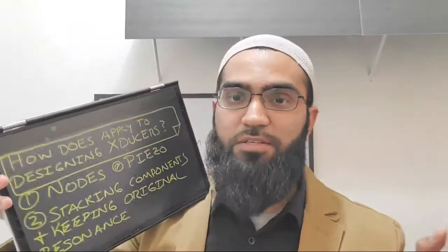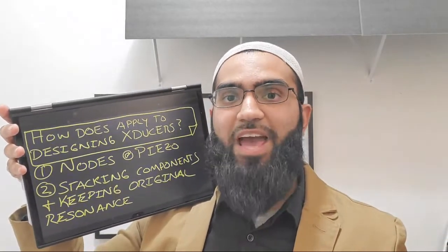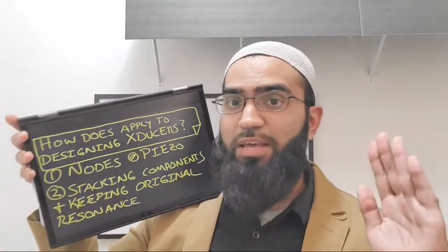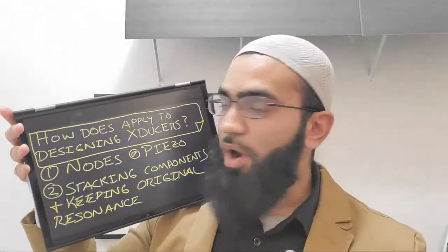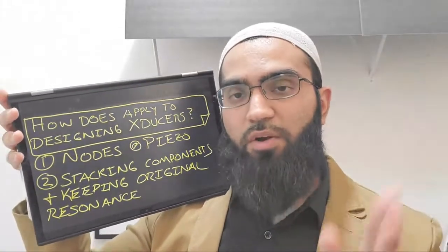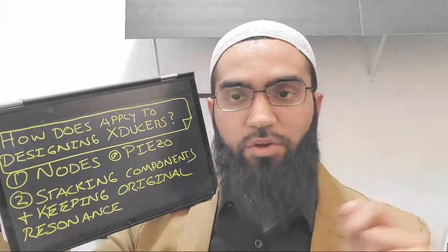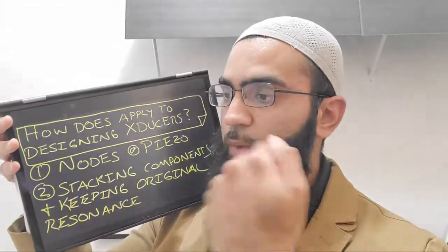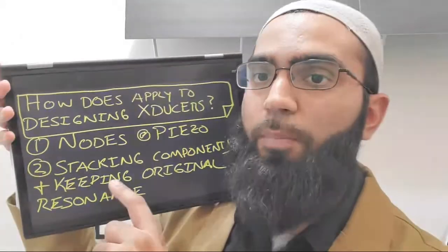Because in some cases, I know for many ultrasonic surgical tools and also for welding transducers, there's many attachments done to the base transducer, and they can get over 2 to 3 times longer by attaching these tools. However, designing that tool according to the frequency of the transducer will then allow you to maintain your optimum form of the mode shape in operation.